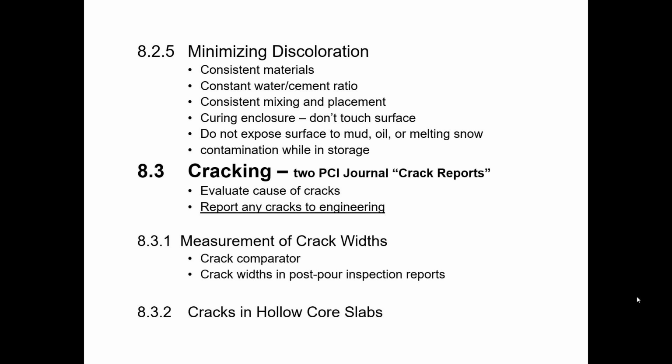Before I go much further, if you look on page 8.12, about the middle of the page, just above section 8.2.5, that paragraph there says, more information about efflorescence is available from PCI. A paper titled Efflorescence on Precast Concrete provides more detail about what efflorescence is, what causes it, how to minimize it, and, not covered in this discussion, how to remove it. I'll just give you a quick overview of that for your own personal benefit, but you should have access to that. If it wasn't part of your materials, it should be available on the PCI website.